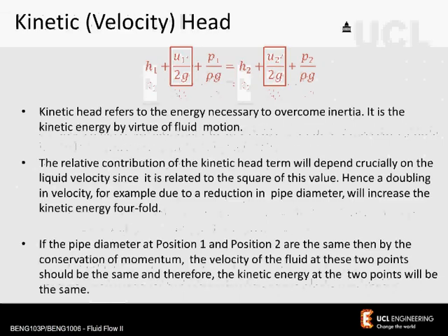The kinetic or velocity head refers to the energy necessary to overcome the inertia of the fluid. So it's the kinetic energy that's generated by virtue of the fluid motion. The relative contribution of the kinetic head term is going to depend fundamentally on the liquid velocity, since it's proportional to the square of the liquid velocity. Hence, a doubling in velocity, for example, due to a reduction in pipe diameter, will increase the kinetic energy fourfold.